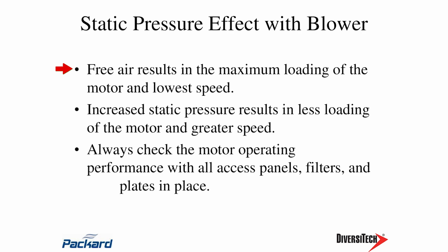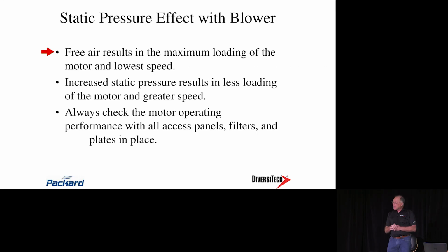What would I expect to happen to that blower operating in that condition? What would the motor reaction be? May go out on the overload protector. And that motor's probably going to run a little bit slower than what its operating speed is designed for. And what would the amps look like? Really high. Really high amps.